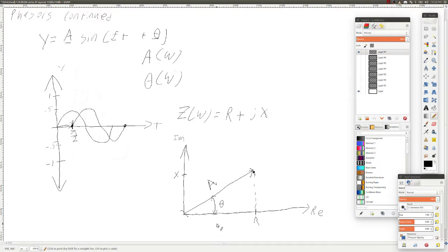Phasors give us a way to represent a signal at a given frequency as its amplitude and its phase without having to use polar coordinates. This means that we can use a lot of the math that we already use without having to get overtly complicated. We can represent sinusoids as simple coordinate points.